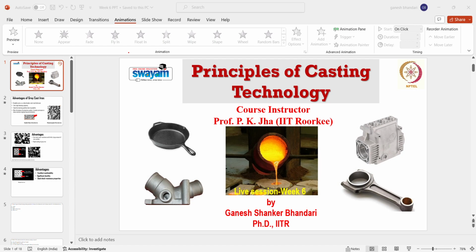And if we are going with aluminium or silicon slags, then it will possess different properties. So there are majorly two practices during smelting operations in a furnace: one is basic slag formation and the second is acidic slag formation. According to that slag formation practice, you have to design the refractories of your furnace. So anyone wants to answer this question?